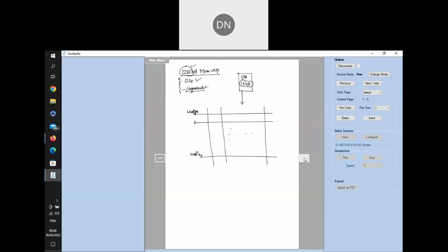Each of these columns will contribute one bit. Let's say bit 0, then bit 7, bit 6. So these will contribute 8 bits for me, and there are 16 words, or word locations, or 16 rows available here. Now, at the intersection of every row and column, one memory cell will be available.